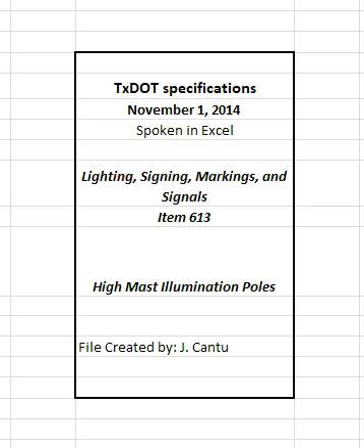3.4.3 Pole installation. Install structures after foundation concrete has attained its design strength as required on the plans and Item 421, hydraulic cement concrete. Coat anchor bolt threads and tighten anchor bolts in accordance with Item 449, anchor bolts. Erect and align the poles within 12 inches of vertical. Use enough temporary slings, chains, or wire rope to prevent unintentional separation of the pole sections. Orient poles so a worker can see into the access hole while facing oncoming traffic.